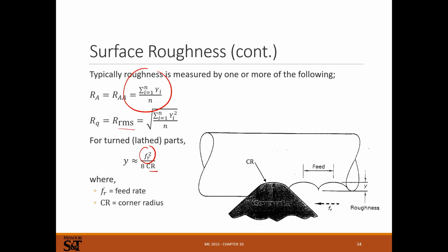And a lot of this, the surface finish, you're not going to sit there and measure every part unless you're doing something very sophisticated. So you don't see a lot of that. Most of the time you'll make a few parts, make sure they're good, check quality on a few parts, and assume that the rest of them are good based on the sample that you measured.